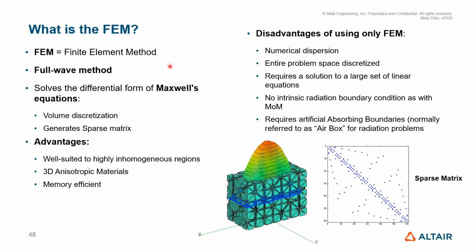As we discussed before, FEM or finite element method is a full wave method, solves Maxwell's equations with volume discretization and generates a sparse matrix, the one I am showing here. It's well suited for highly inhomogeneous regions. So each tetrahedral you can assign a different dielectric material. So it can be as inhomogeneous as you want it to be. And of course, you can also include 3D anisotropic materials because the formulation is very straightforward in FEM. So it can also be memory efficient because of the sparse matrix we have.